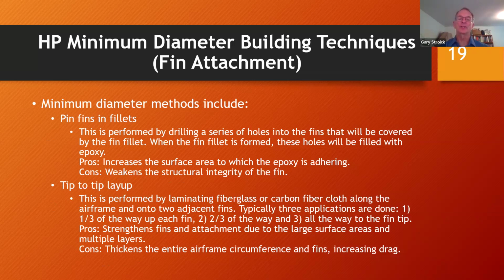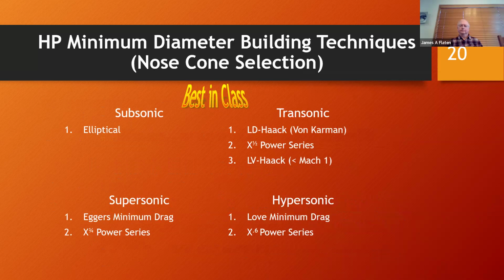The con, of course, is you are thickening the airframe around its circumference, and you are thickening the fins, and so you are increasing the drag. Increasing the drag, if you're trying to go as high as possible, is not ideal. But losing your fins on the way up isn't ideal either. So anyway, these are 2 techniques you can consider using. All right, let's move on to the next one.